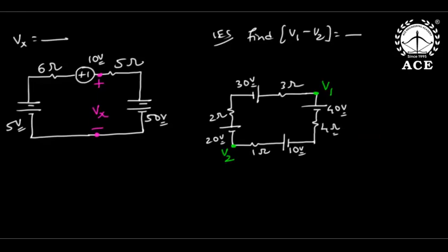Okay, I'm going with solution C. I need voltage Vx, which is the open circuit voltage across the target terminals. There is no element here, but to find Vx, I need to write a KVL. To write a KVL, first I should know the voltage across the passive elements, so first I will do mesh analysis.